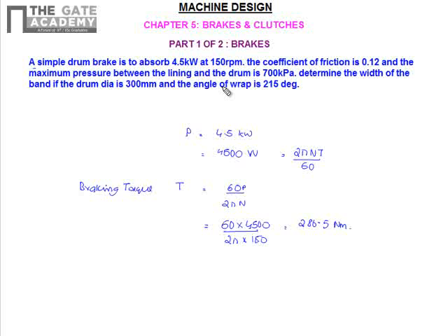Now this is the braking torque given. So what is this braking torque in terms of the frictional force? This braking torque is given by mu times the normal reaction. What is the normal reaction? It will be pressure into area.